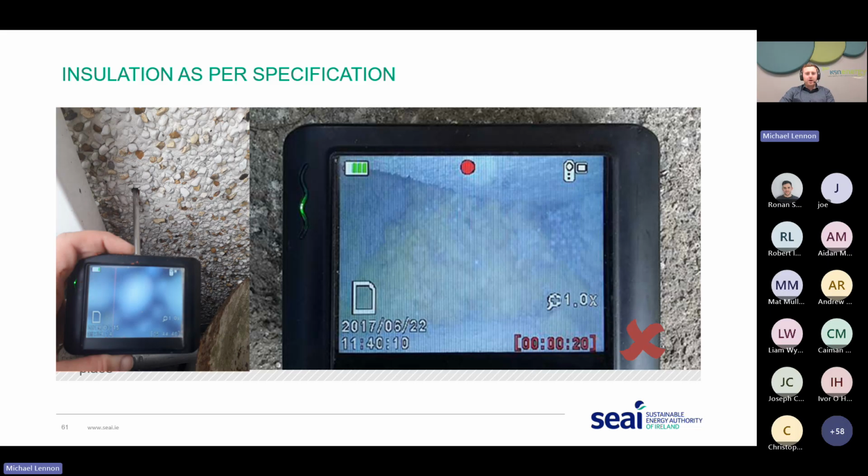Just be mindful as well of where existing fibre is present in the cavity. If there's existing loose fibre material, for example, the cavity is already going to be filled with insulation. So again, you must check against your NSAI certificate for the product as well, just to confirm that it can be certified. There are different types of fibre materials, fibre batt materials, loose fibre materials. It all should be checked as part of your initial survey on the property, whether it's suitable to be filled.